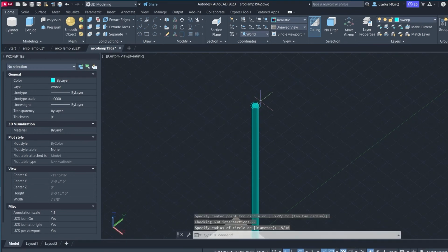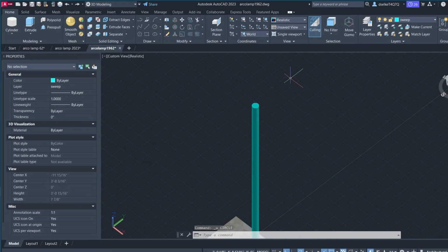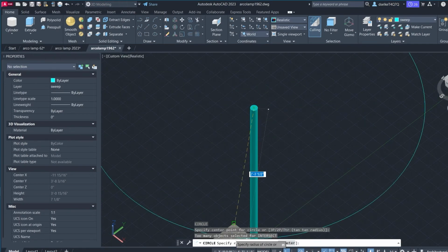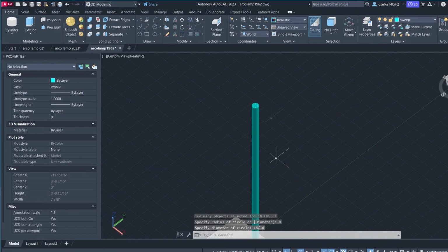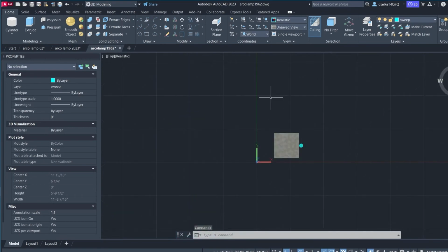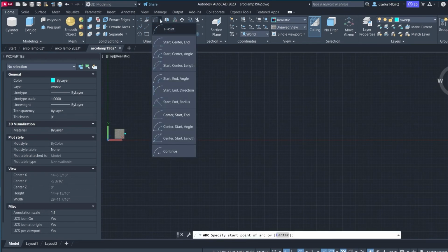And so now we're going to draw the next piece of the sweep, which is a 15/16 inch circle to start with. 15/16 inch diameter circle. So, oops, not radius, it's diameter. So let's undo and do that again. Undo, that's Control Z. You circle again, center point, change it to diameter, and the diameter is 15/16.